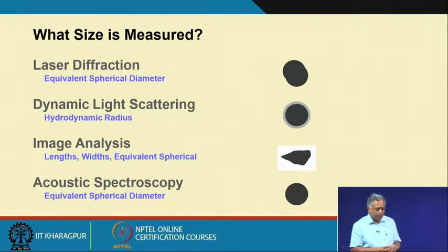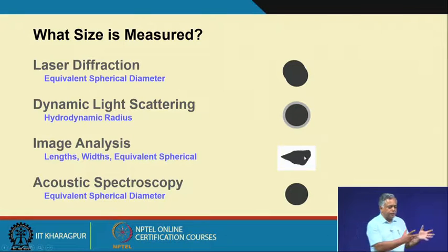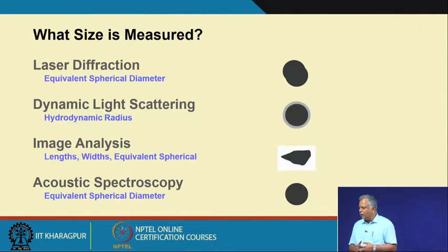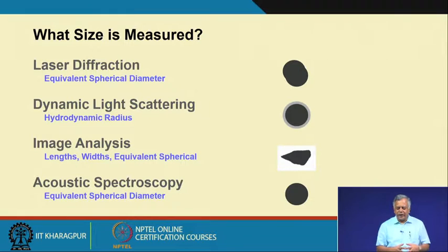When the particles are in coarser size ranges, they are transported through the most common bulk material handling system, the conveyor belt. On top of that you have a camera. So, you get the images, process those images, and send the information to the control room about the size distribution of the material being transported.